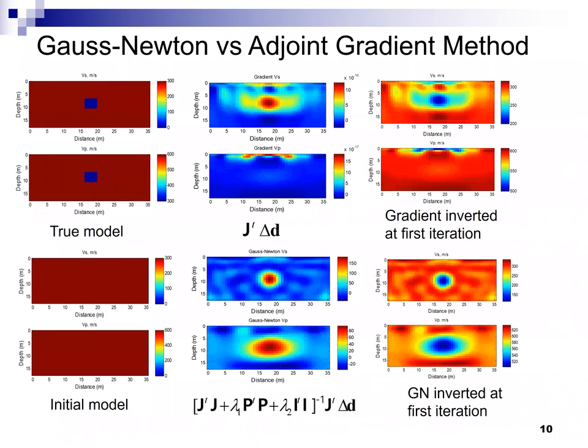So we have 3 columns. The very right column is the reconstructed material. This is the inverted result for the first iteration: you get the initial model, subtract this one, and you get this one. This is the shear wave and P wave profile. We don't see anything from the cross-adjoint method. What does this second column mean? This is the gradient vector. You get the initial model, subtract the gradient vector times a certain step length, and then you get the inverted result.